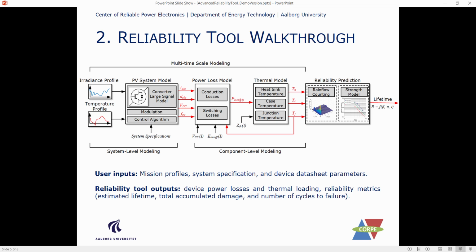Next, the device power losses can be translated into the junction, case, and heatsink temperatures according to the employed thermal model. Finally, the thermal loading of the device can be used in order to determine accurate and valuable reliability information such as total accumulated damage or an estimated number of years of lifetime. The tool, together with the graphical user interface, have been built based on MATLAB and have been packaged as a MATLAB app. This will allow the user to simply initialize the tool from the MATLAB application toolbar.